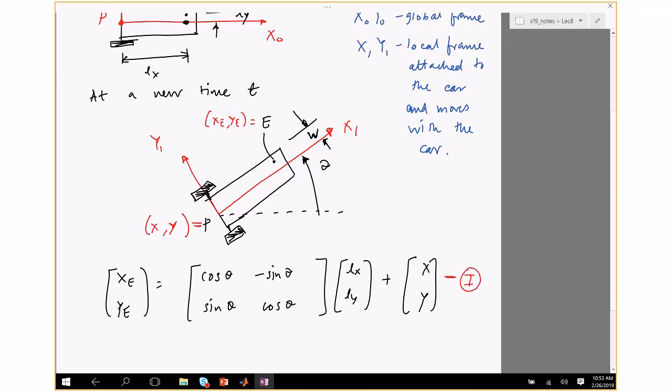Okay, eventually we are trying to get xe, ye to follow a path. It could be a circle, it could be a different curve, it could be your initials, whatever you want. Now, what you want to remember is the only thing you can control for a car is the speed of the wheels. For the manipulator it was easy because you could just control the joint angles, theta 1, theta 2, theta 3.